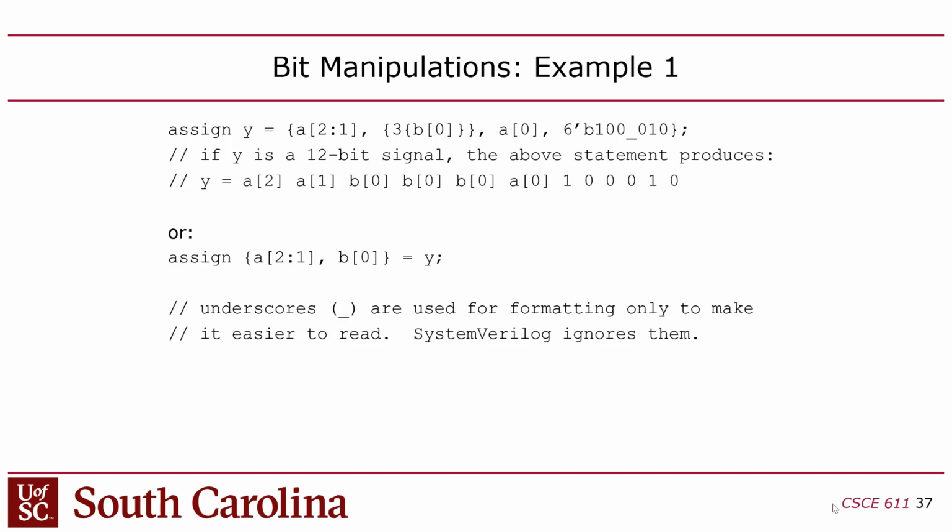Yes? Why do you need external curly brackets in this case? That's the syntax, and you actually do need those external curly braces. That's just the syntax for duplication. Next to A0 you don't have it. Right, because I'm not duplicating. Oh, so it's only for duplication. It's only for duplication, yeah. You have to use a double set of curly braces for duplication. But the outer braces are for the concatenation. The compiler is looking for that syntax for duplication. So you can't do a shorthand and just say 3. If you eliminate the outer braces, you'll get an error.